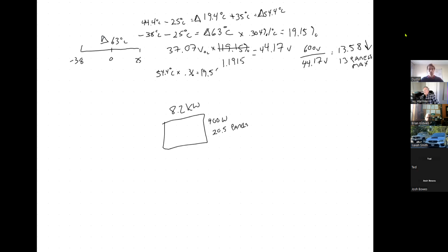So on the hottest day, it's going to produce 19.58% less voltage. Less than what? Well, we're going to use VMP, not VOC, because we want to use not the worst case scenario, but the normal case. So we multiply that times 100% minus 19.58, which is 0.8042, or 80.42% decimalized. So what's 31 times 0.8042?